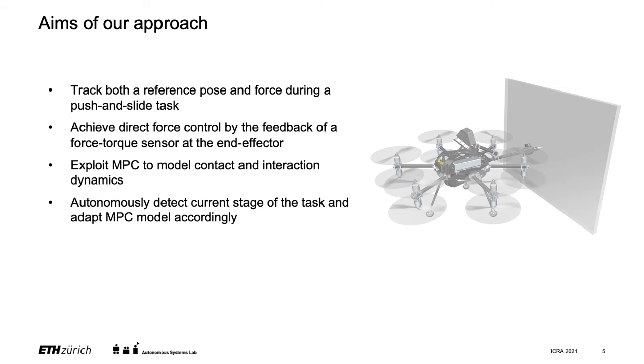First, we want to track a pose and a force reference during a push and slide task on a plane surface. Second, we want to fuse the measurements of a force torque sensor at the end effector to achieve direct force control. Third, we want to apply principles of friction physics to model the interaction in the NMPC. And fourth, as the interaction dynamics naturally change during the task execution, the controller should autonomously detect the current stage of the task and adapt the NMPC model accordingly.